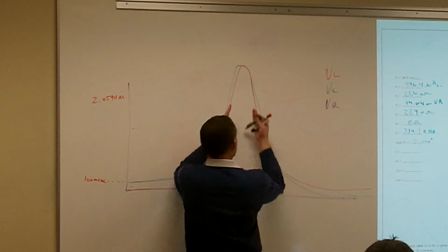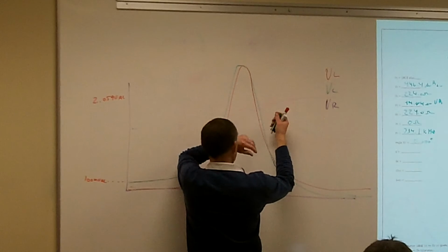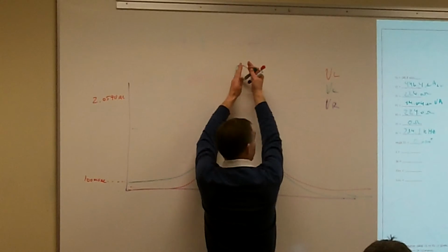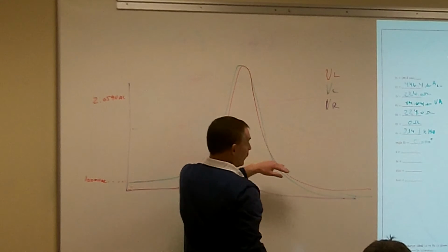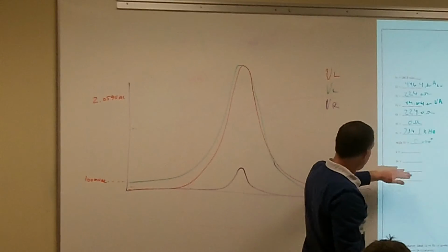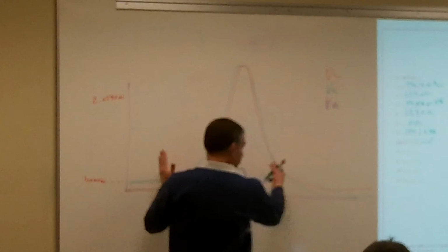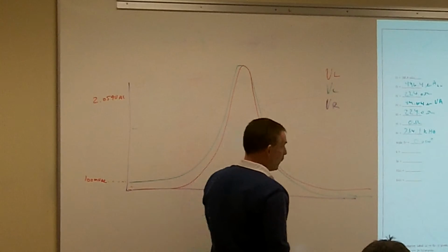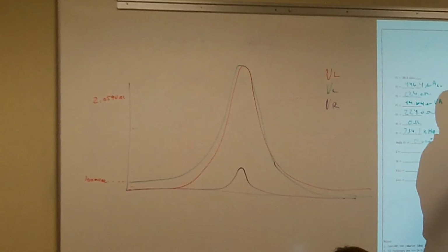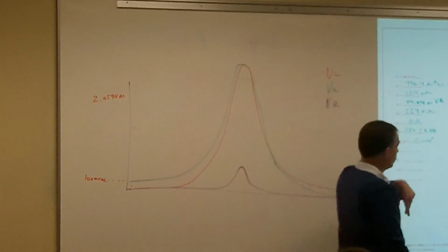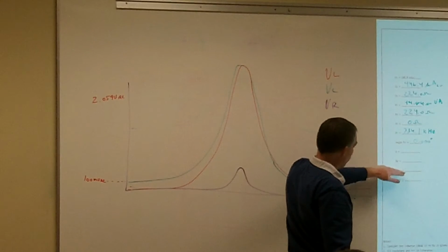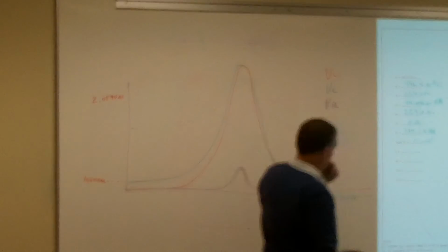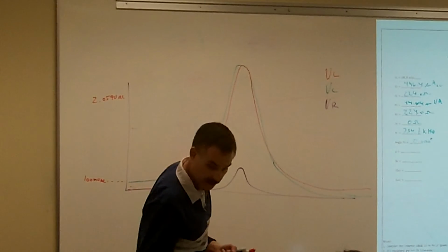If I have a very good Q, then on the one that I was just showing you with my spreadsheet, it's very straight up, very pointed. That's going to have a good high quality circuit. And that quality depends on what our bandwidth is. And our bandwidth is going to be what's our allowable frequencies that we allow coming out of our output. And remember, our output has to be something greater than 70.7% of our voltage source. And then we want to find out where at the bandwidth is my lower frequency cutoff and where's my upper frequency cutoff. So to calculate out your quality then,